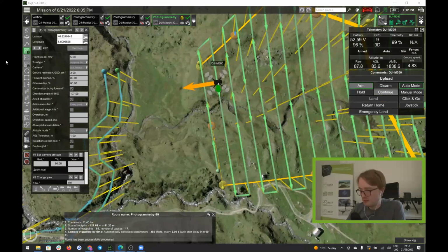So the way it worked was that, let's say you enter in here 10 degrees, it moves 10 degrees downwards. If you enter minus 10 degrees, it also moves 10 degrees downwards. So it's just how the DJI mobile SDK interprets these messages. And yeah, in that case, at least it wasn't possible for us to move the camera upwards automatically. If you need to do that, maybe it makes sense to try to move the camera manually